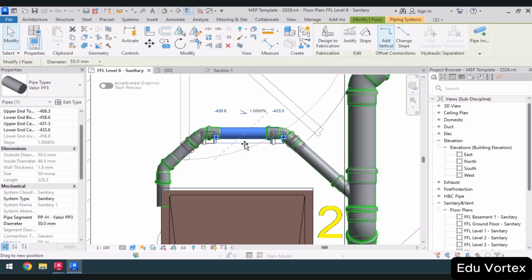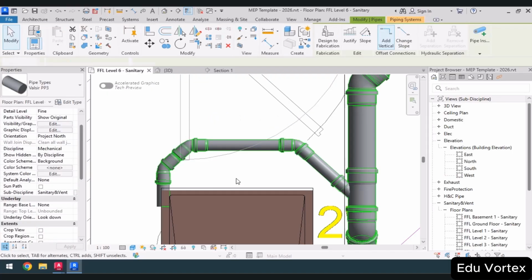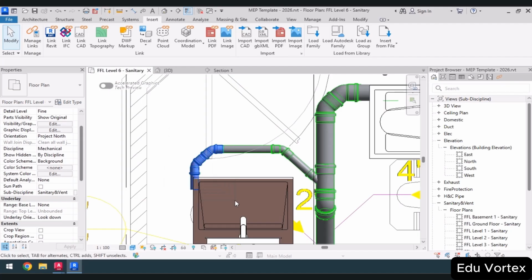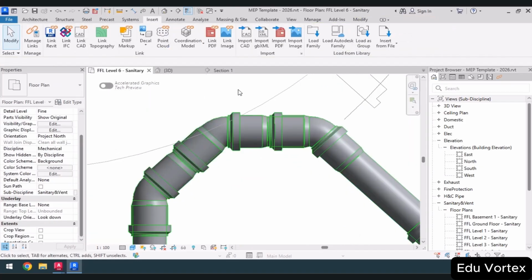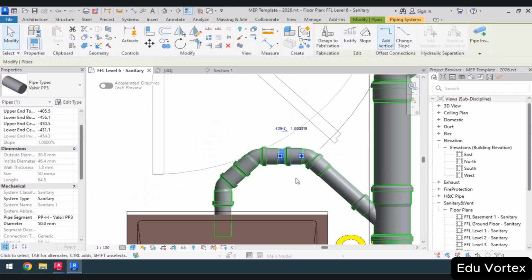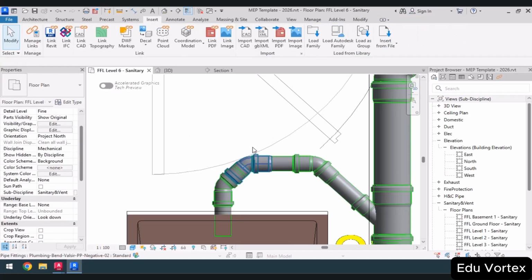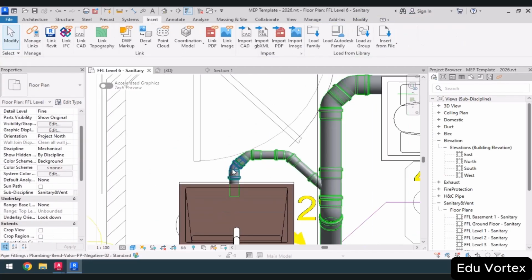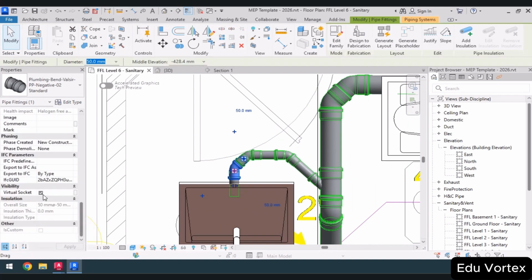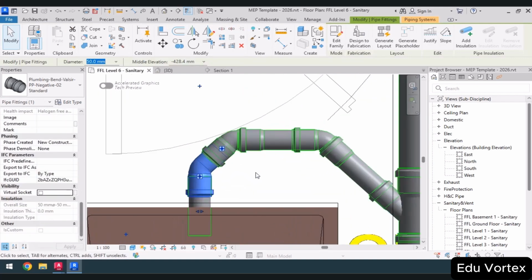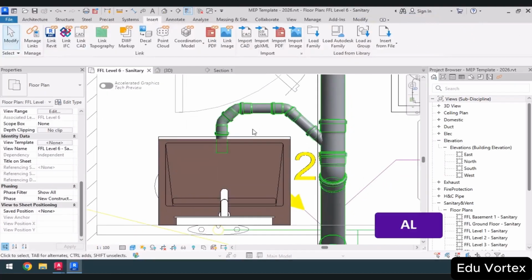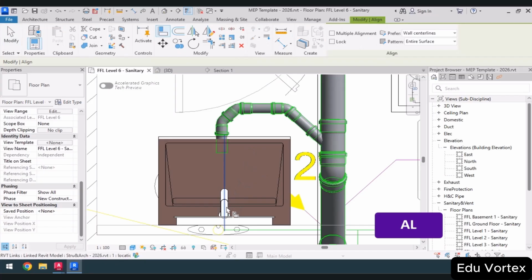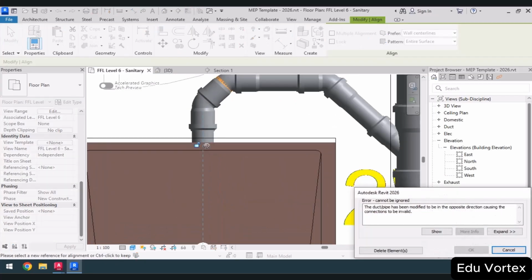Alternatively, I could lower this pipe piece as much as possible while keeping its alignment in mind. So I will also shift this piece of pipe downwards. This one. And this one is that I shifted this piece downwards. You can choose this elbow and check the virtual socket option. If you don't do that, nothing major happens. It just improves visual clarity. So now using the align command AL, I will align the sink axis with this pipe's axis.